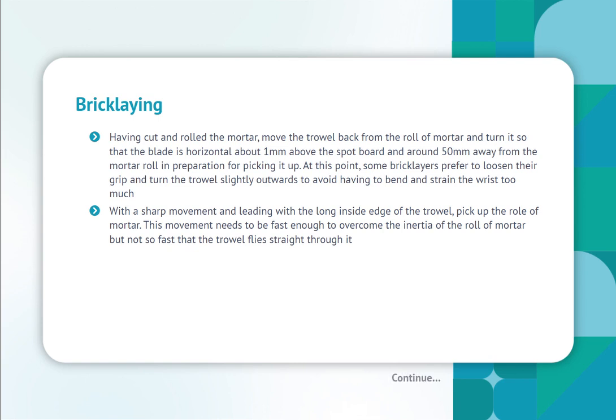With a sharp movement and leading with the long inside edge of the trowel, pick up the roll of mortar. This movement needs to be fast enough to overcome the inertia of the roll of mortar but not so fast that the trowel flies straight through it.